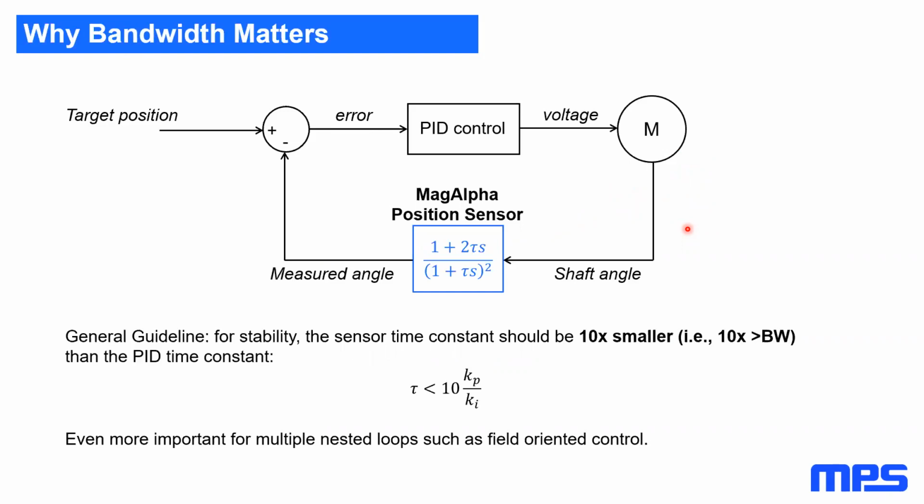Well, because in a control system, oh man, we're into some fun stuff now. We're in the S domain, the Laplace domain. You've got a time constant. Our time constant for our position sensor is here. Our transfer function is here. And that time constant is completely linear with the cutoff frequency. So we could be talking in terms of cutoff frequency or just tau, the time constant.